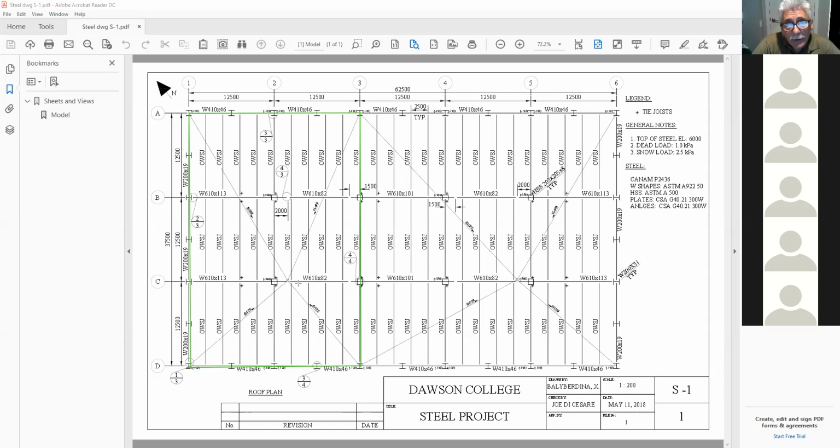Sir, so at the bottom, it's going to be a steeper slope, I guess? Well, it doesn't matter, because you want to make sure the minimum slope is 2%. So, for example, in this direction I get 2%, but in this direction I'm going to end up getting 4%. Who cares? You follow? As a matter of fact, I want to maintain a minimum of 2%. Here, if I get 4%, all that means is that the water is going to run to the drain much faster than this one.